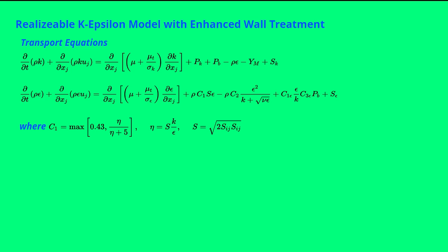Because the entire crux of the simulation revolves around the added heat transferability of a turbulent flow, it was imperative that this be captured in the model. Therefore, the realizable k-epsilon model with enhanced wall treatment was used in Fluent. It models the effect of turbulent fluid structures using transport equations to capture the macro scale effects.